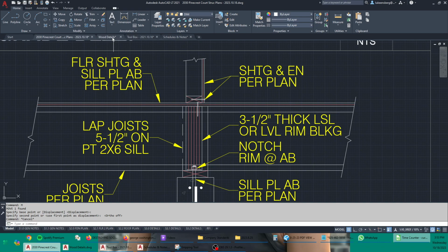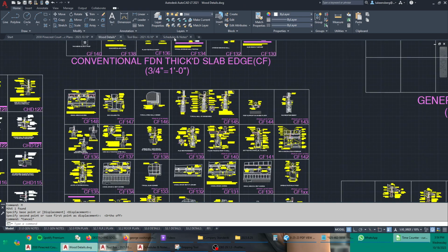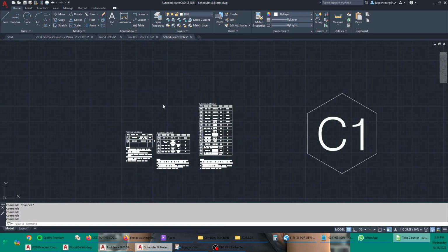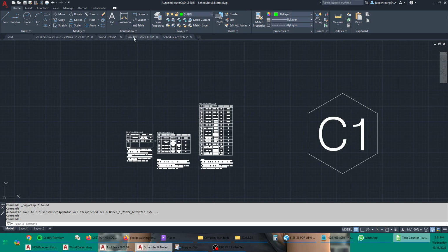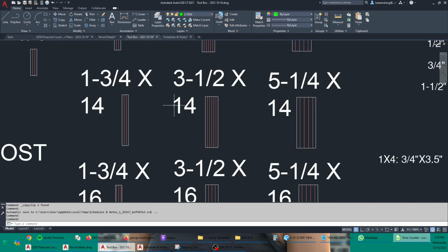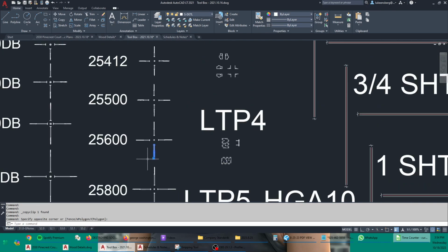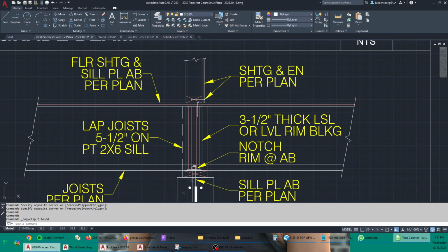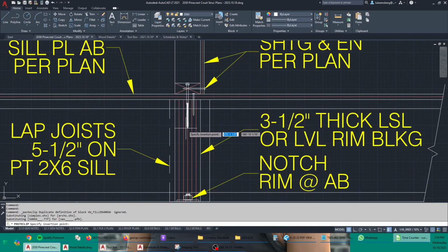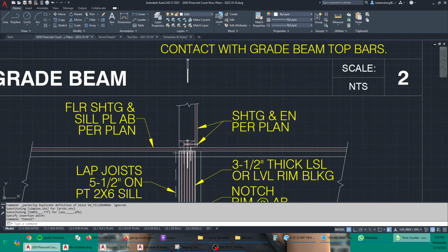And then we need shear wall anchorage into the rim blocking, so we can specify some SDS screws for that. Perhaps 5.5 or 6 inch long screws should do. Here or here. Get both of them. And let's see. Does that work? Yes. And I'll delete the other one.